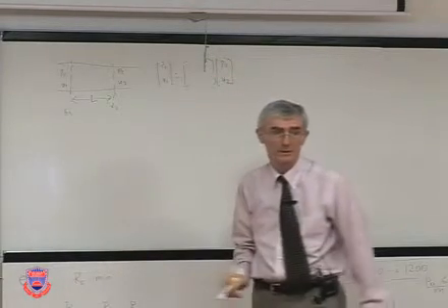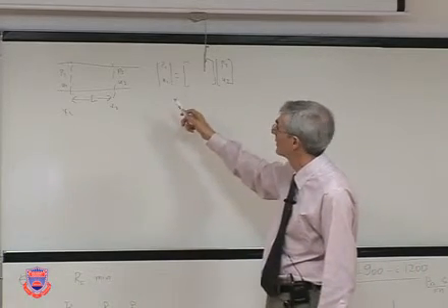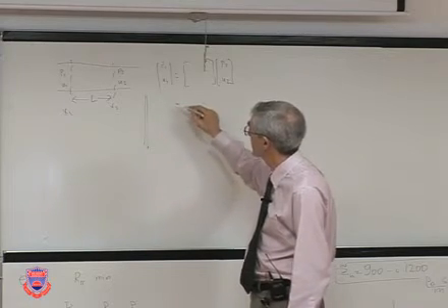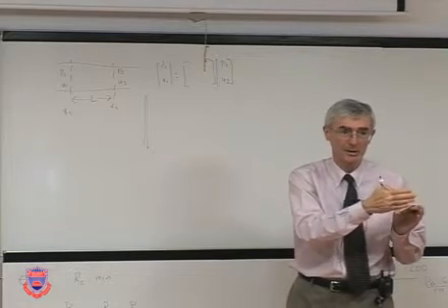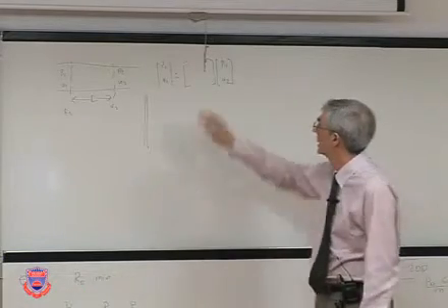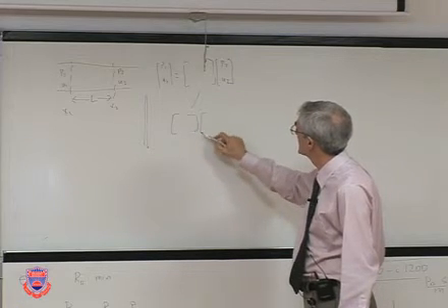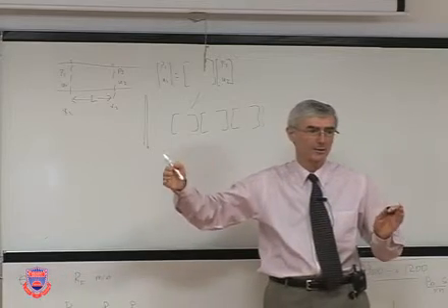Expressed as a matrix. So you have these matrices you can develop for a silencer, for a membrane, for a plate, etc. To calculate the sound pressure, especially in a computer, all you have to do is put these matrices side by side, just the way they're organized.